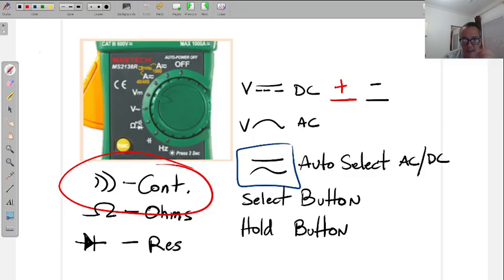So when you turn it to the other setting, it's just going to give you a more precise number. And when you actually measure, it might be 7.6, not 8, or 7.2, not 8. Sometimes this is important for us to know, because you're dealing with small variables. On a 20 amp breaker, the difference between 16 amps and 19 amps is only 3 amps, but it makes a difference on that breaker.